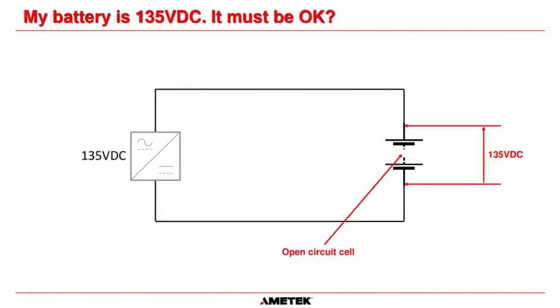And the most obvious failure that can happen, obviously you're not going to remove a battery and expect your battery to be okay. That's rather silly. But if you have an open circuit in that battery, it is as if that battery is not there, because power cannot flow through that battery or from that battery. Okay, so if you have an old battery that has an open circuit cell in it, it is as if the battery is not there.